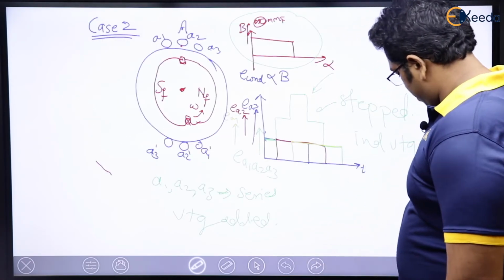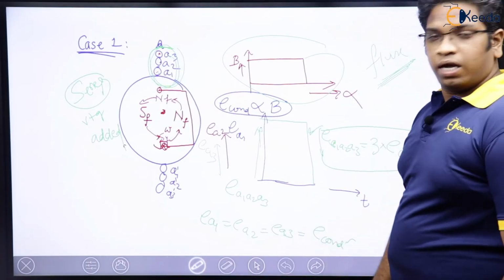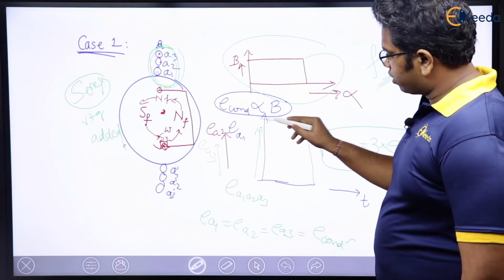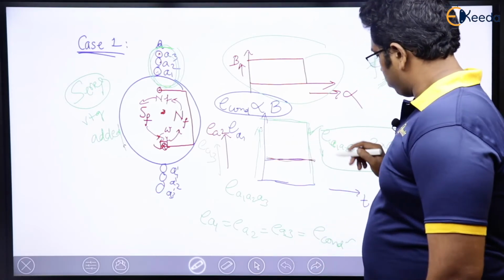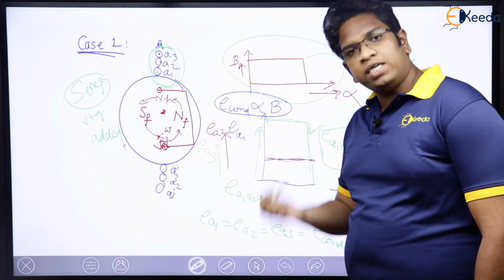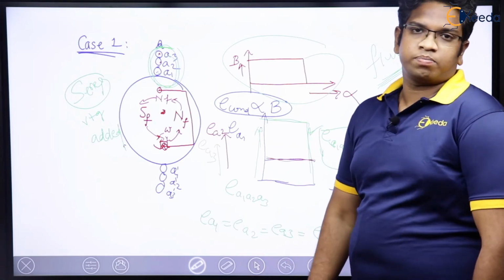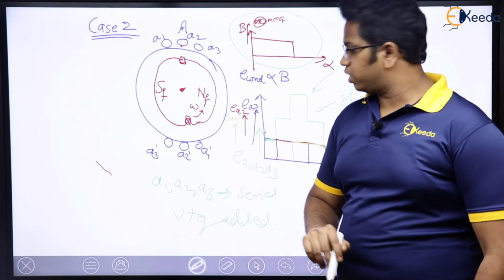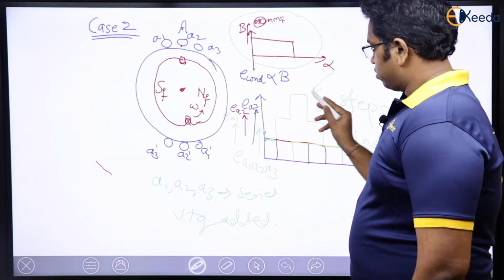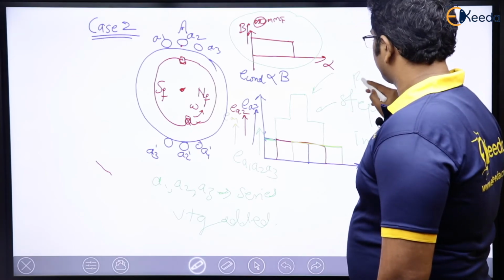But here you had all three conductors in the same slot, so you got induced EMF this way. If you think of EA1, EA2 and EA3, you got only one single step for the same flux density. And here, for the same flux density distribution, you got stepped, which means it is a better sinusoid.